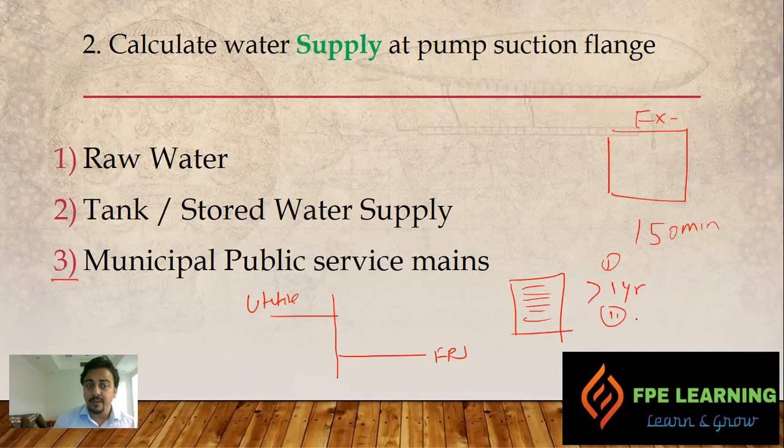So for example, in the summer, during morning, Monday morning, everyone is going to school and office, and the consumption of the water for the utilities is higher. So at that case, you have to take your hydrant flow test. So make sure that if the fire happens at that moment, these two combined can go without any problem, right?